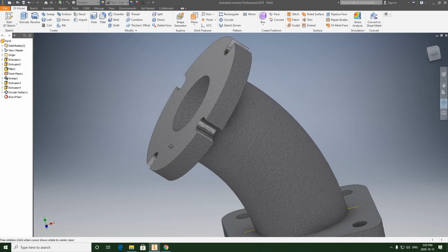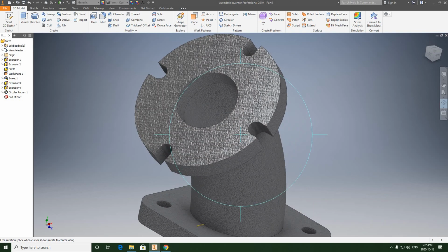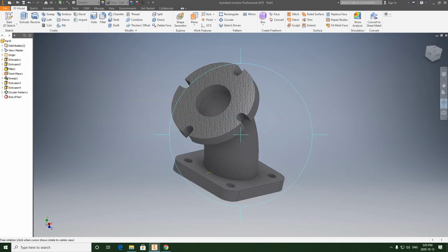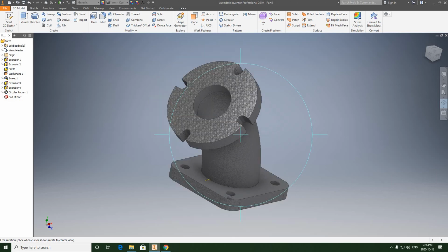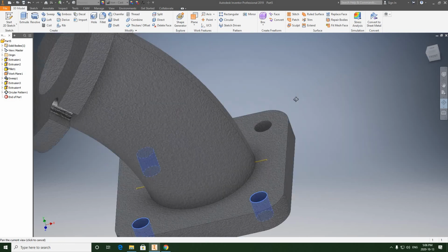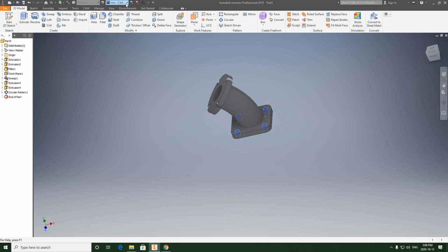Those slots definitely have to be machined, and this face needs to be milled off. And it shows that the interior of this is cast with a rough texture. And also, these holes here, we can make them machined 2 as well, but we'll make them machined 3, which is basically a crappy drilled hole. So we'll go back up here and hit machined 3.